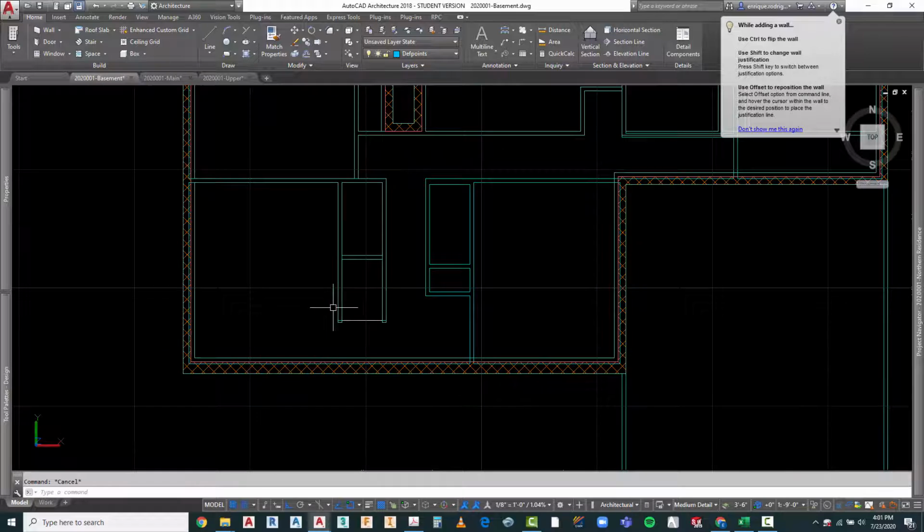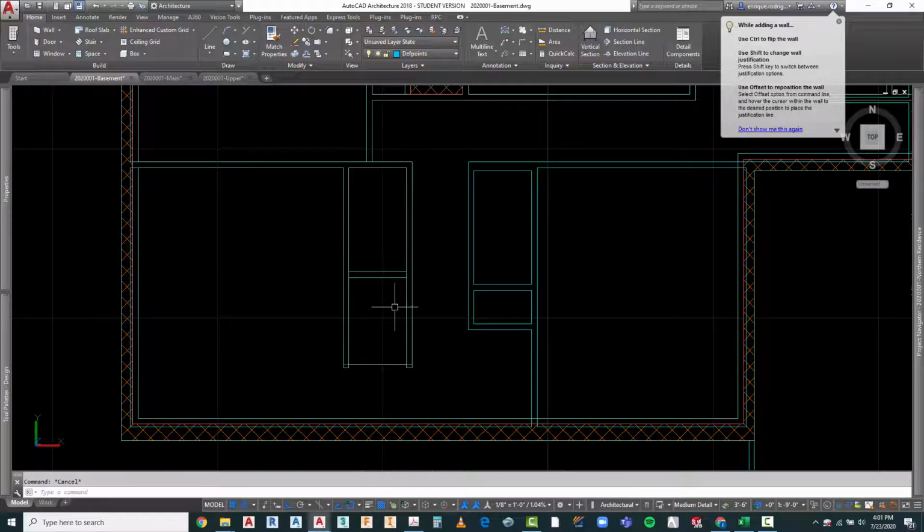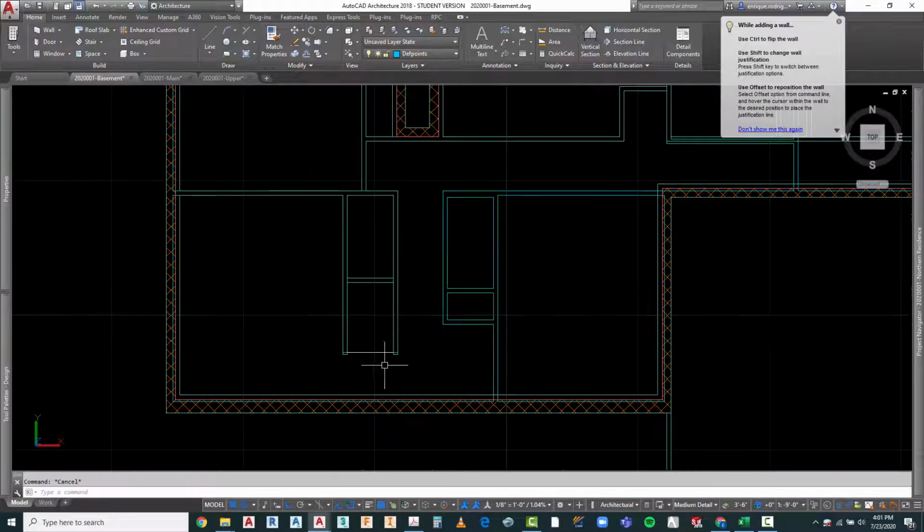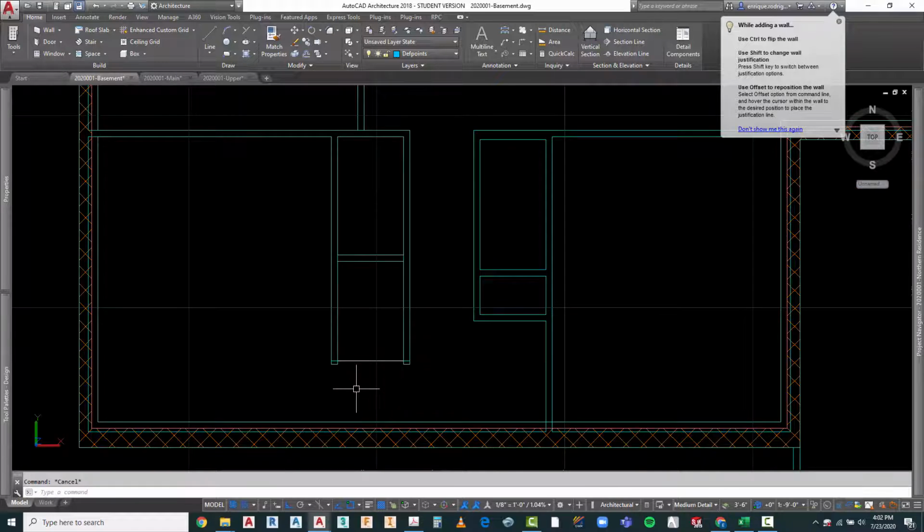to modify that. Now one of the things that is going to determine exactly what the solution to this problem is has nothing to do with this distance, but it has to do not only with that distance but also how much horizontal distance we have for our vertical flight of 9 feet, so that we can keep our treads long enough to feel comfortable as you're going up.